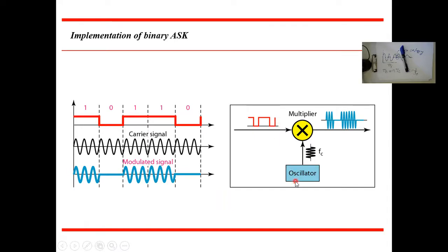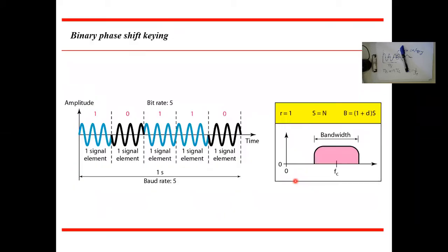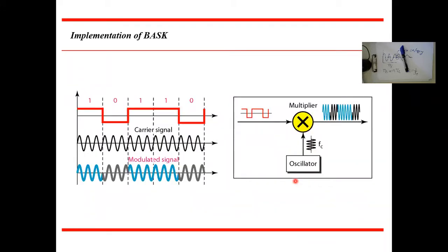Now let's make use of our line coding techniques. What if we represent our signal in a polar representation, if you remember these polar representations with 1 and -1? So now if you have this polar representation and multiply your binary digital signal with your carrier, you will end up with a binary phase shift key. Because 1 times the carrier gives the carrier, and -1 times the carrier gives the anti-phase, which is the 180-degree phase of the carrier.